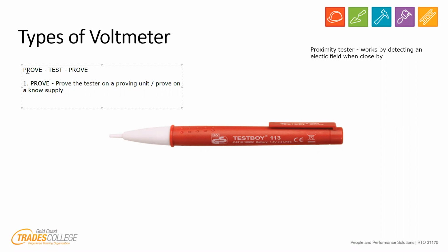So I get it out of my pocket. It may have been in there 6 months and I haven't done any work. I go up to a socket in the kitchen and hold it against the socket and it lights up. Okay. So I've done my isolation and I hold it against the cable, for example, that I want to cut. That's the test part.